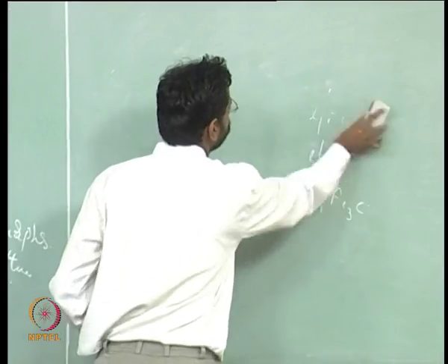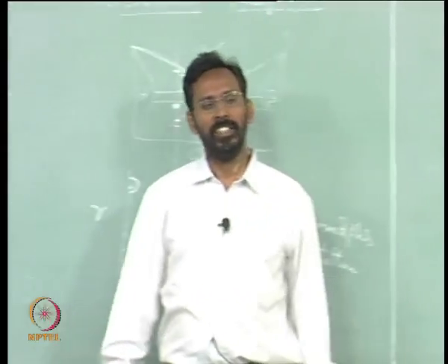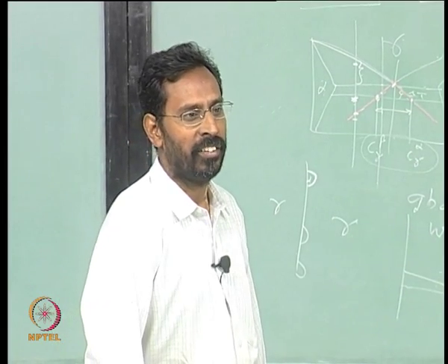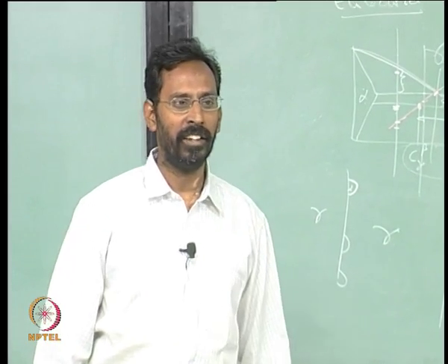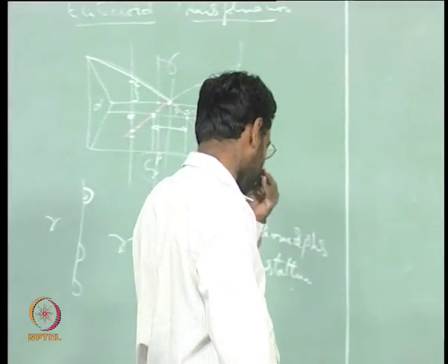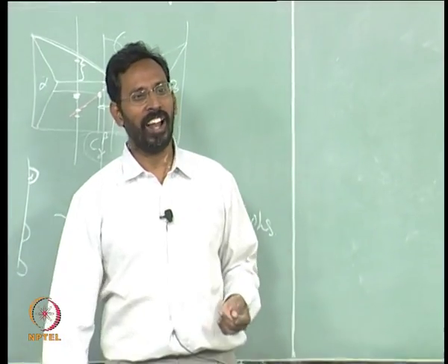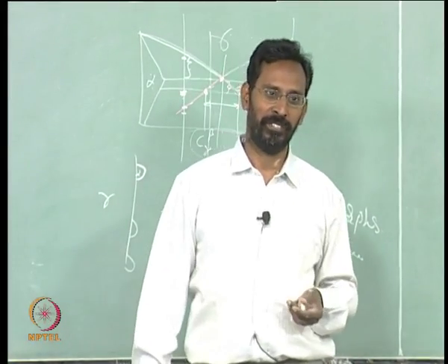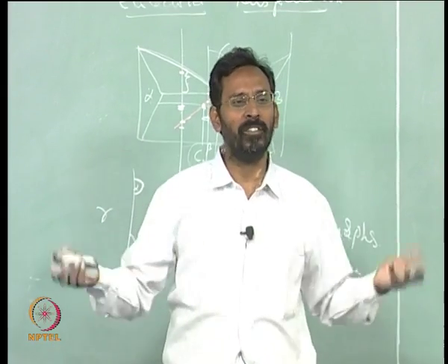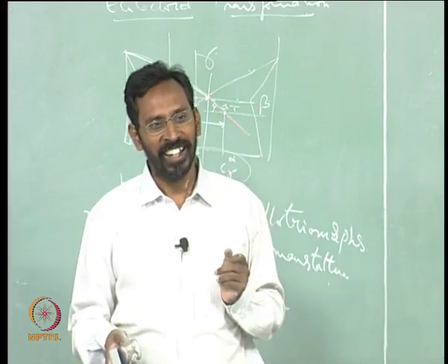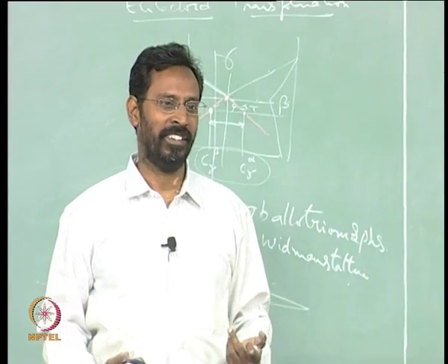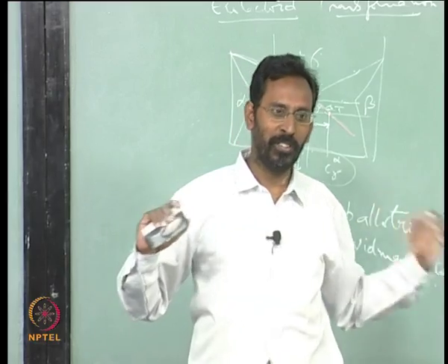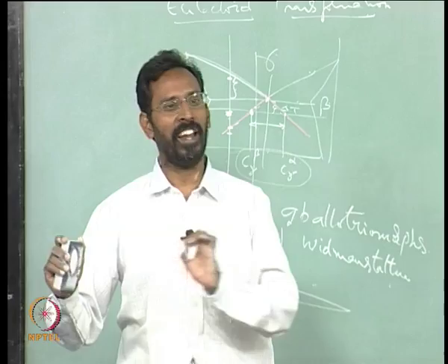So, we see reversed eutectoid. If you want to call it a divorced eutectoid, in principle bainite is a divorced eutectoid, isn't it? There is no lamellar structure. It is an interesting question. We do not actually call it eutectoid because it is not happening that way. If that is the case, in the cementite formation, a eutectic reaction where cementite is coming out first and the remaining liquid is becoming gamma, can I call this eutectic? Because both of them are not forming at the same time. So, ultimately you have to see the final microstructure, liquid giving two solids finally. Similarly, gamma giving two solids finally, one is ferrite, another is this one.